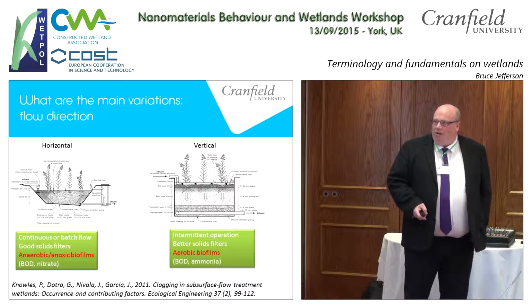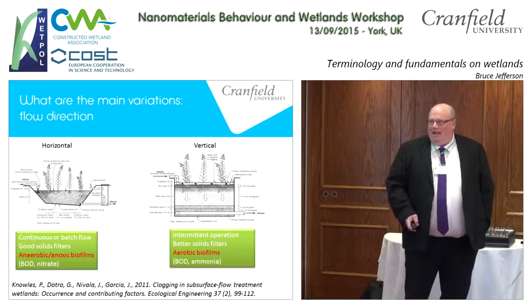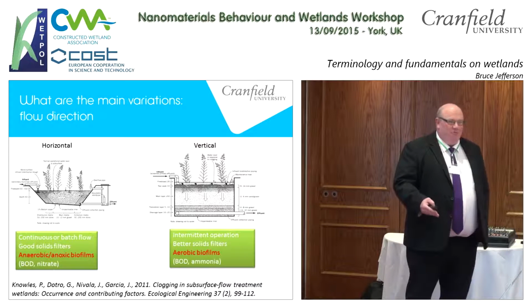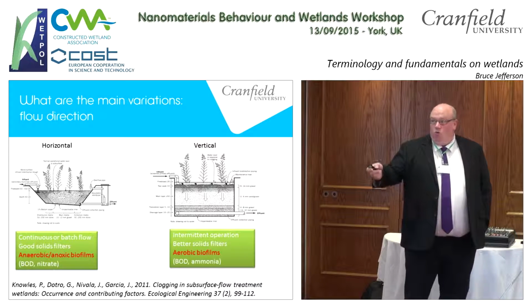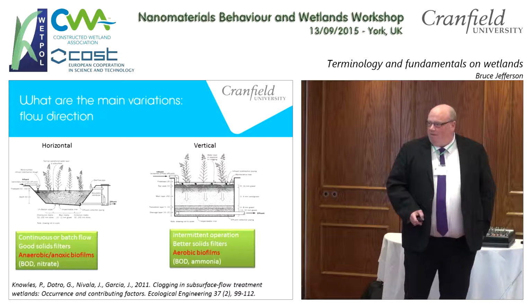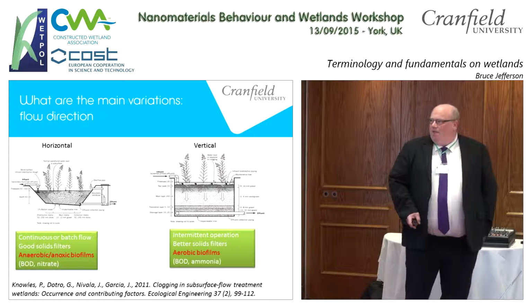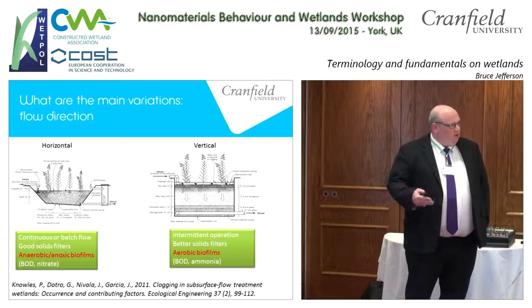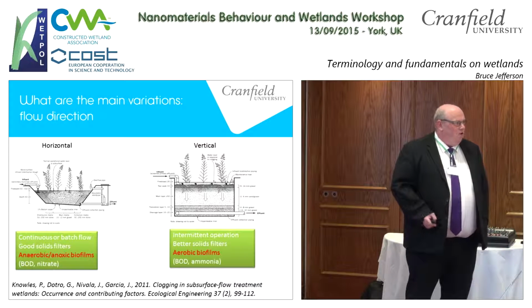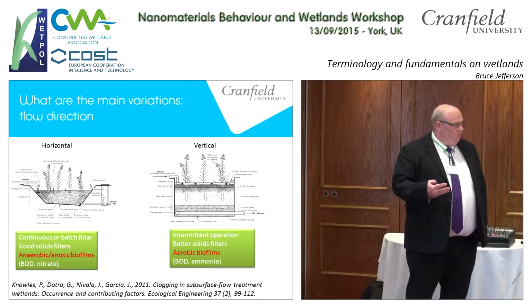The other thing we have to think about is our redox chemistry. So I say in the UK we've tended, and in other parts of the world, but in the UK especially, we are almost quite taken by horizontal subsurface flow tertiary wetlands. There's quite a lot of them around. And of course then elsewhere, we'd see a lot of vertical flow wetlands as primary, secondary wetlands for main sewage treatment purposes. Now of course the vertical flow systems, which are intermittent, you flood them, you drain them, are very aerobic.